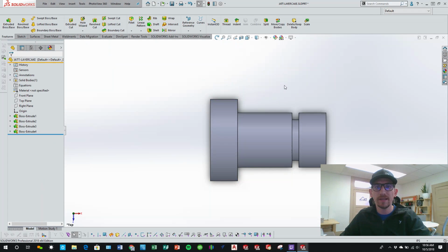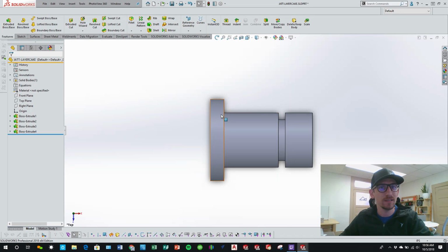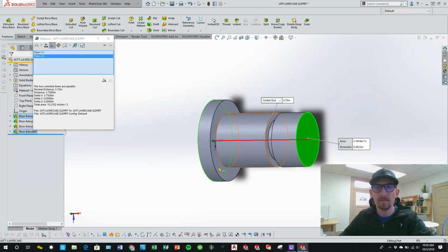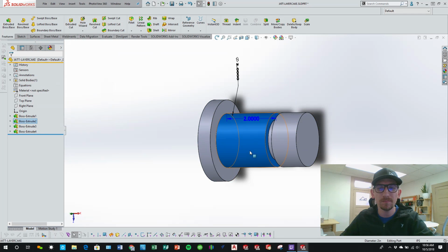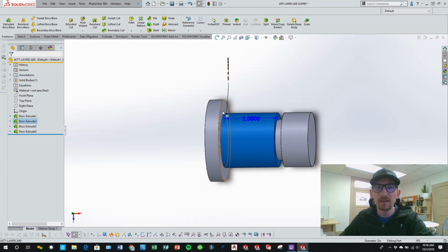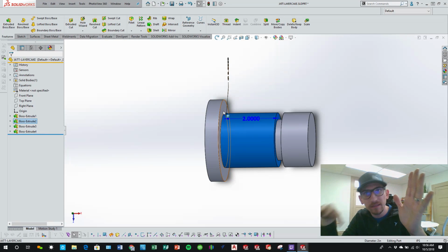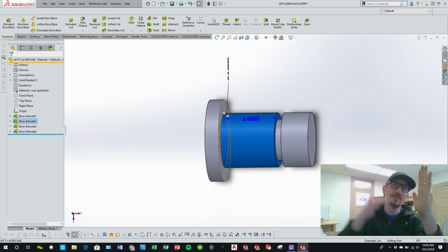Do a Control Q on that. Oh, so this got skinnier, but did we still retain our dimension of 4 1/4? No, it dropped down to 3.75. Now, why did that happen? Well, it's because each of our 3D dimensions that we have here is based off of the existing face, the prior feature. So if we affect any of our prior features, it will affect the post features.